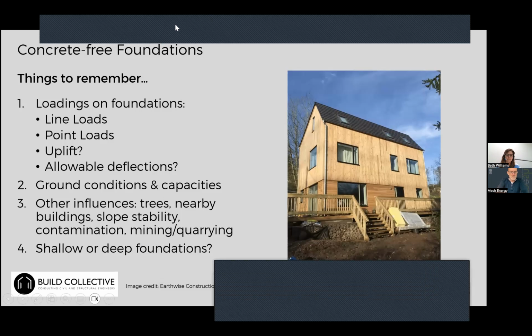Question here: have you come across dense plastics or composite materials for piles and ground beams? They are not quite as strong as steel, but they can have bigger sections and they do not rot or corrode. Yeah, you can do sections of glass reinforced polymer, and you can get similar section shapes to steel I-beams and angles and that kind of thing.